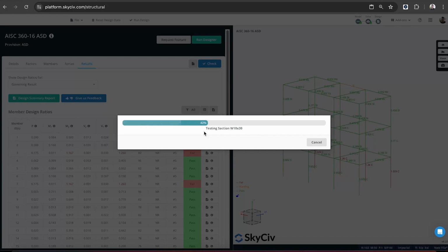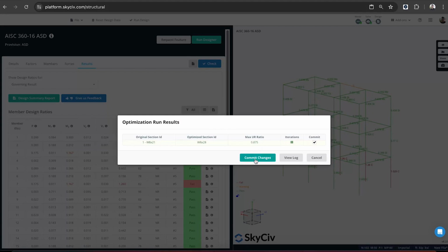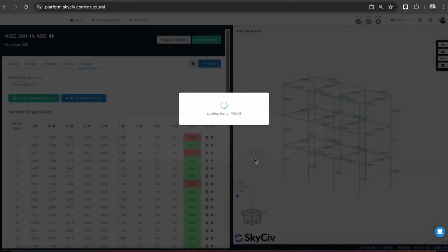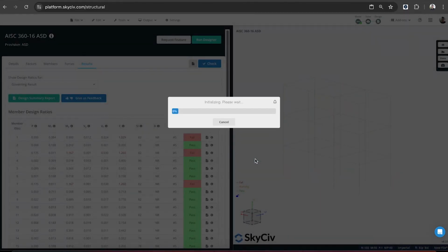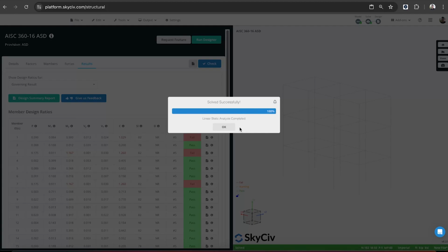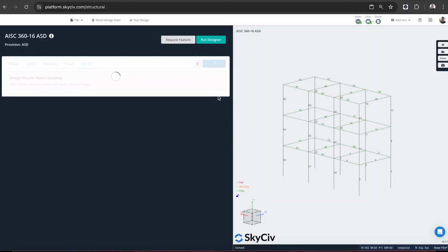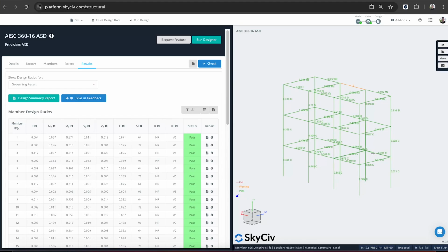So it should have a more up-to-date analysis for each of the sections. So you can see it does take a little bit longer, but it should produce a more accurate result. And to get it to work each time, you would set it to 1. 1 is the best, because we'll always rerun the analysis in between every cross-section. But just for the sake of this demonstration, I think it's just sort of saving some time, just using a higher analysis interval. And you can see the difference that made now.